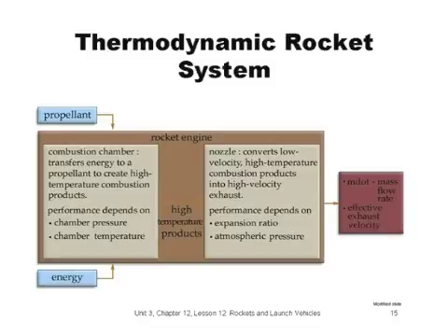We can see the various inputs, process, and outputs of a thermodynamic rocket. Propellant and energy combine in the combustion chamber to produce high-temperature combustion products. The nozzle converts these high-temperature products to high-velocity exhaust. The nozzle performance depends on its expansion ratio and the outside atmospheric pressure. The final output is high-speed flow that produces thrust. Total thrust depends on the mass flow rate, or mdot, and the exhaust velocity.